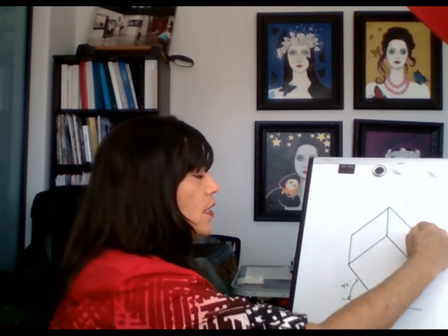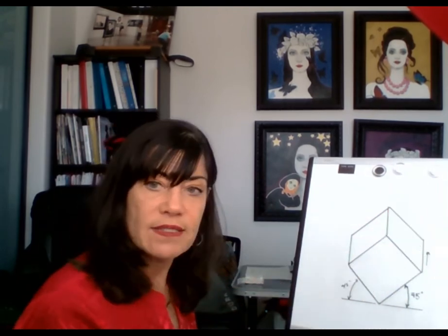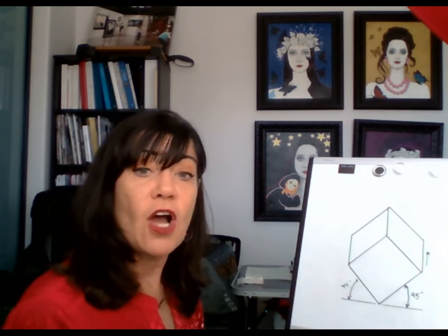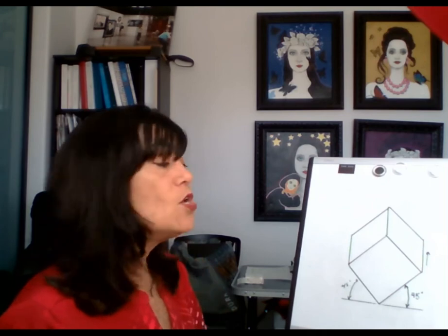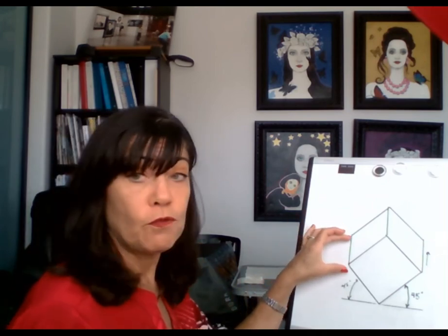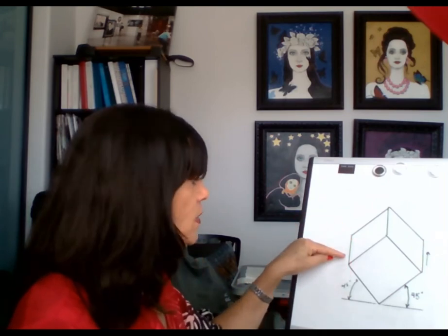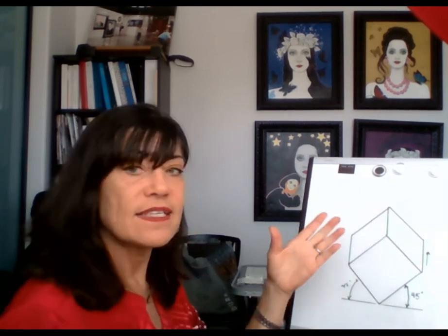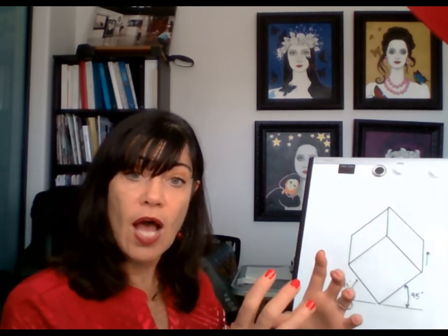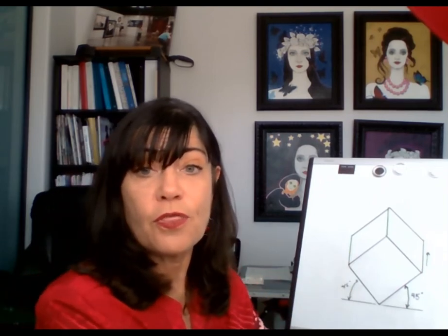I horizontally or vertically brought up lines, and I got the information that this particular block was 4 feet. So I was able to take my scale, put 4 feet, and then once I did 4 feet, 4 feet, and 4 feet, and connected the lines, suddenly this block became three-dimensional the moment I turned it at an angle.